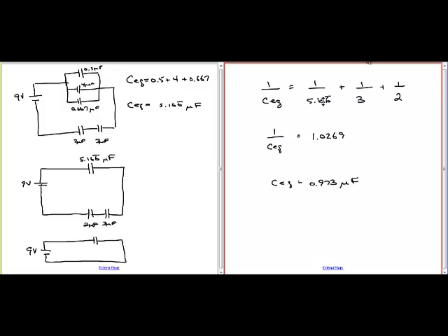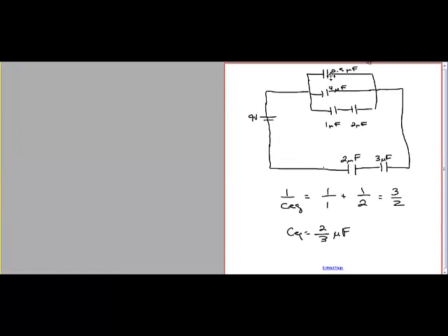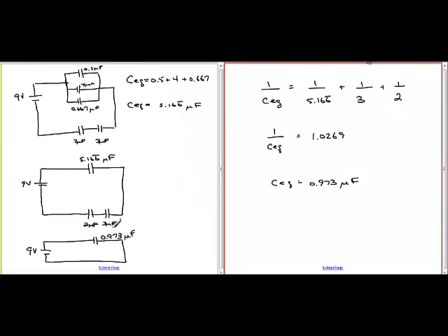This should be less than each one of these individually, and it is. So we're looking at the numerators here, denominators. So is this less than either of all those 3? Yes, it is, so at least that's correct. So if you go over here to the left, the equivalent single capacitance value, which is the same as the original combination of 1, 2, 3, 4, 5, 6 capacitors, is 0.73 microfarads.